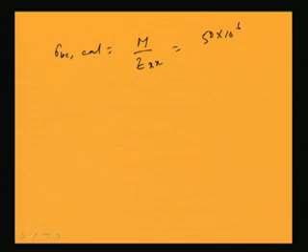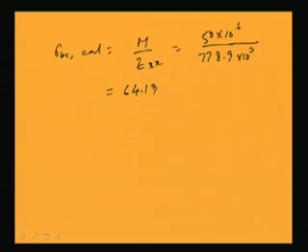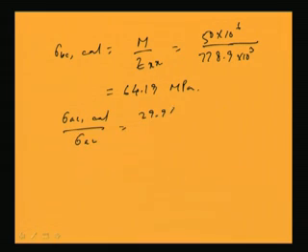Now we have to calculate the sigma BC calculated value. This is M by Zxx. M is 50 into 10 to the power 6 and Zxx is 778.9 centimeter cube. So we are going to get sigma BC calculated as 64.19 MPa. Again, sigma AC calculated is 29.98 and the permissible value sigma AC was 52.62, which we have calculated.